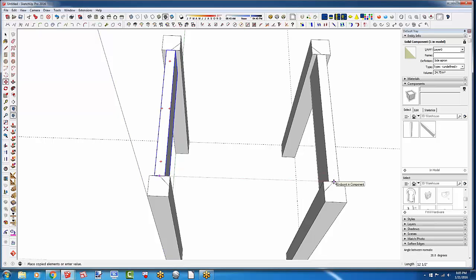So this precision thing is entering numbers when you have to. It's drawing things to fit between what you've already placed. I've seen at least 2 different tutorials out there where they suggest drawing each part separately and then moving the parts together to assemble it. But then you'd have to know how long the apron has to be before you could complete drawing it. Here we don't care. It's just got to fit. That's all there is to it.